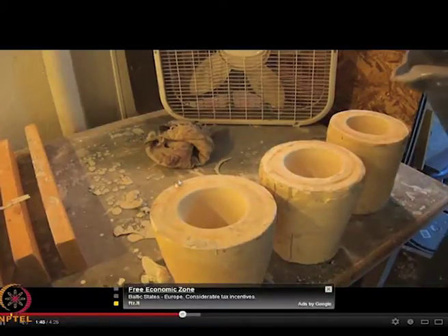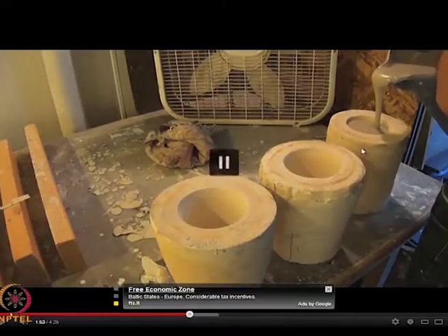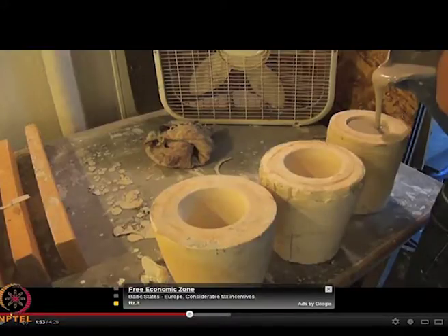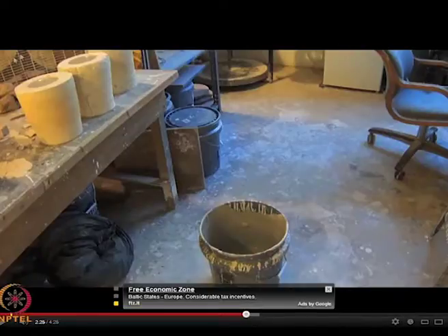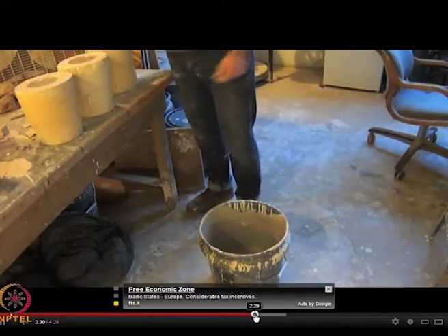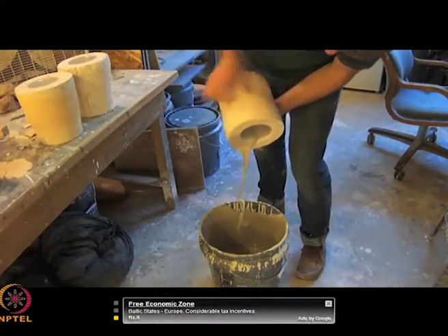Now, these are the molds, which are basically the porous molds I talked of, and they are pouring the slip over there. This mold is filled up, this mold is filled up, and then they are being allowed to stand over here. What happens thereafter is, after a certain length of time, he takes a mold and drains the excess liquid.